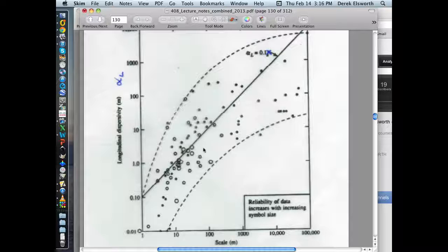If you did that for a whole bunch of other sites, whether natural contamination or human-induced contamination, doesn't particularly matter, and you plotted up the magnitudes of, say, the length of the plume in meters, in this particular case, and you plotted up the magnitude of the dispersivity you got from this. So this is D_L equal to molecular diffusion plus the velocity which you have in your particular aquifer times this thing that you'd perhaps think is kind of a material property, right?